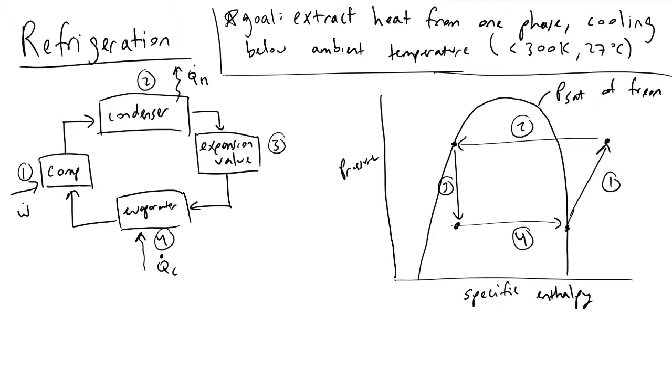And what's happening is inside here, the Freon exists as a liquid. And outside of the saturation pressure, Freon exists as a vapor. And so at these boundary points here, the Freon is in between, but generally you will want it to be entirely a vapor if you're passing it through a compressor, and if it's going through a pump, you're going to want it to be entirely a liquid.